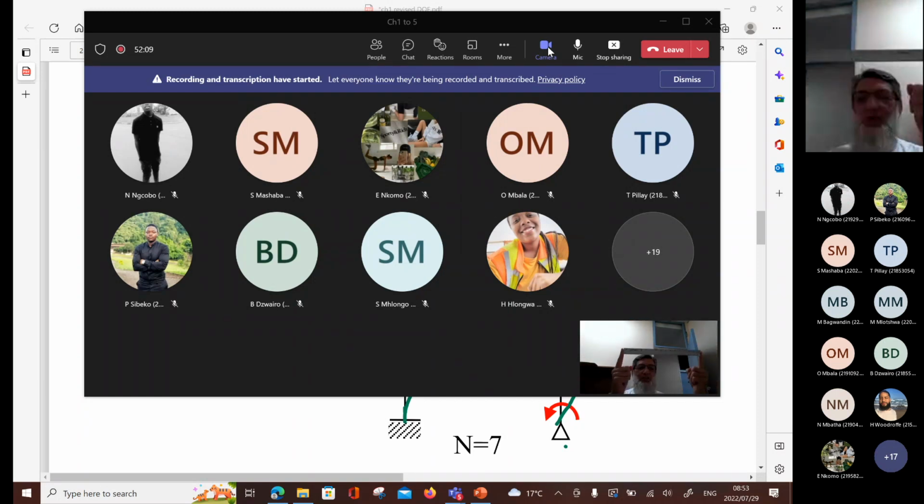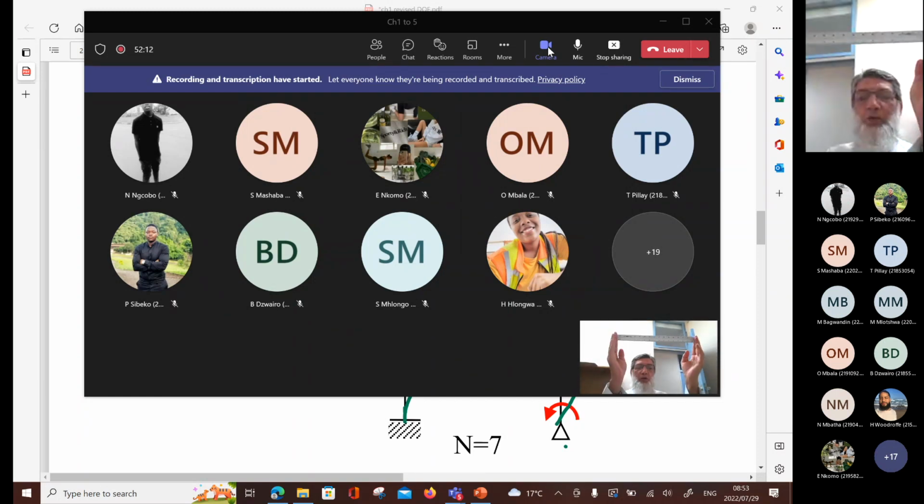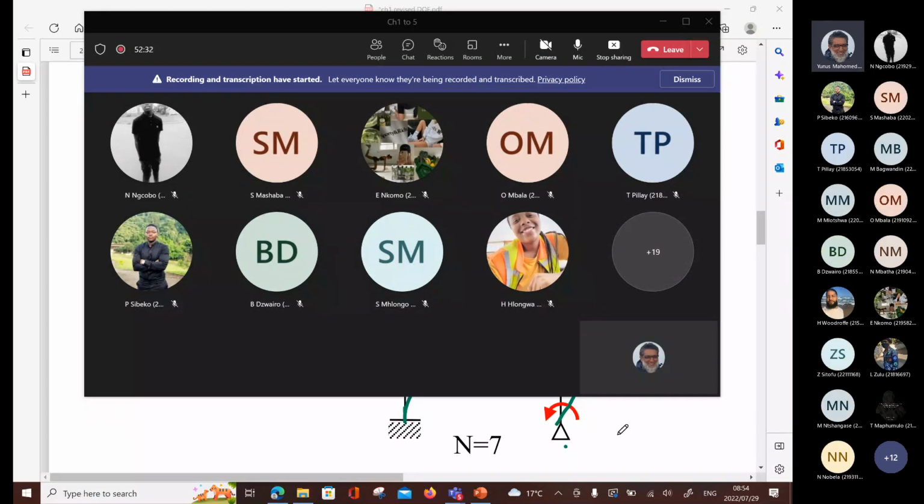All right, so what I'm saying to you is, look at this. There's my portal. This scale rule, okay, is now my beam. So if I move it laterally to one direction or the other, can you see that the length is not changing, which means the deflection at both ends has to be equal. Okay, so that's what we're alluding to there.